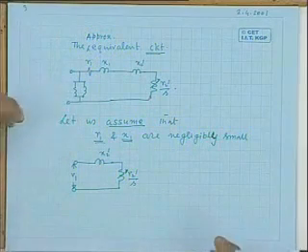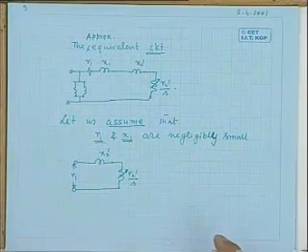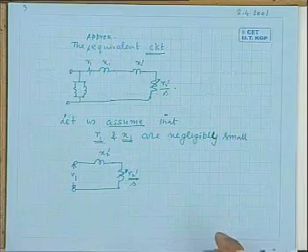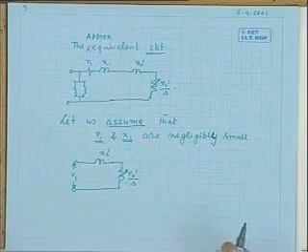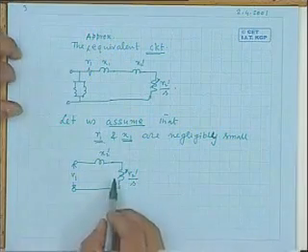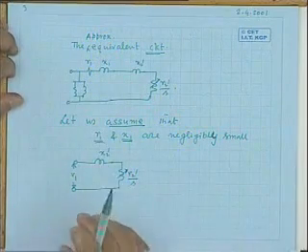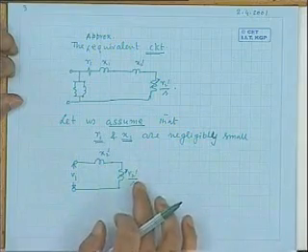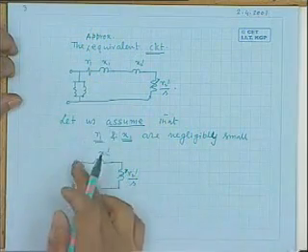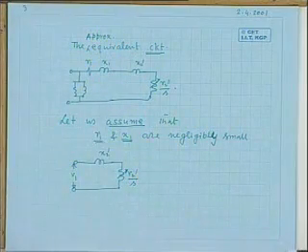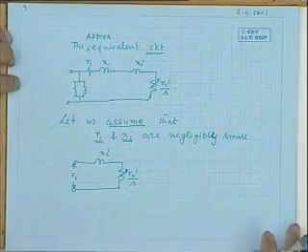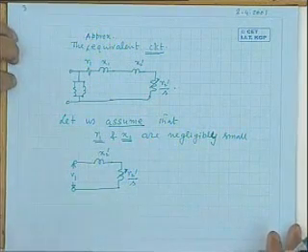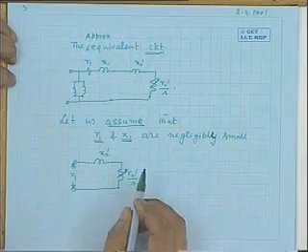Whether it is possible to bring out the salient features of the induction motor so far as its operation is concerned, that we try to do. So in this very simplified equivalent circuit of the induction motor, where only rotor parameters have been assumed to be present and stator impedance and core losses are neglected, it will be like this. Now we can find out the expression for the torque developed by the machine.